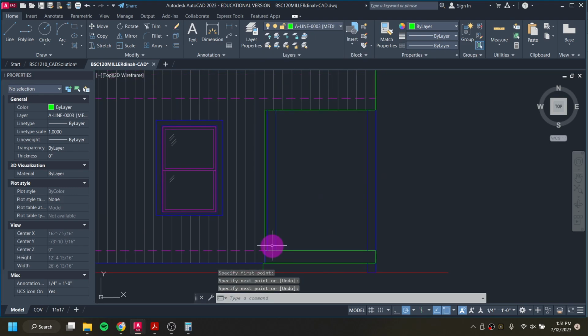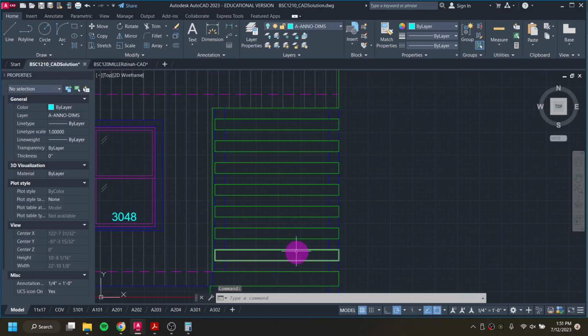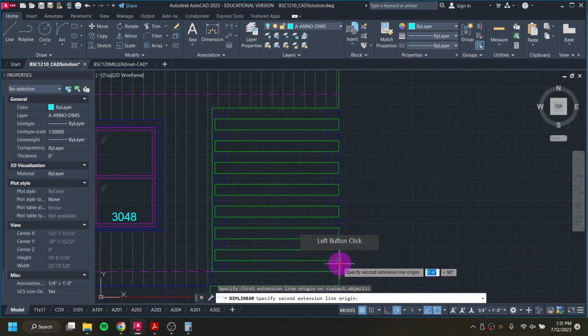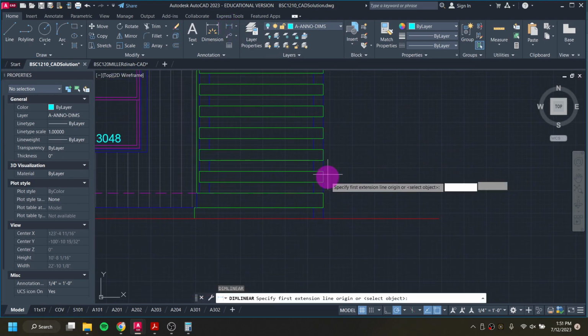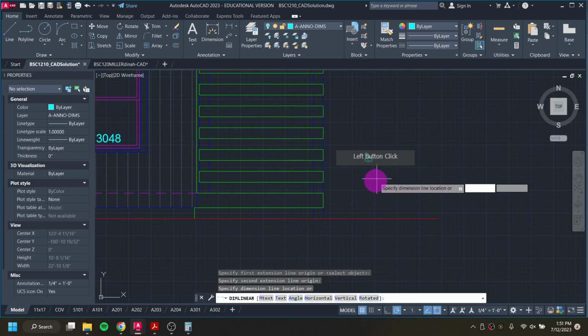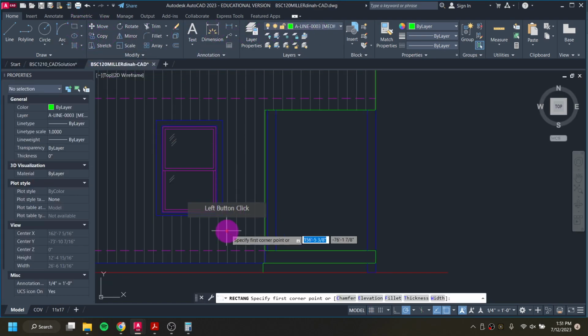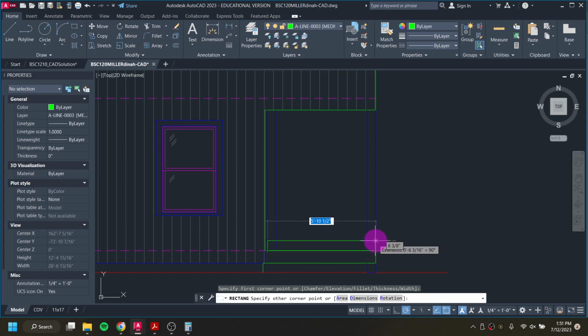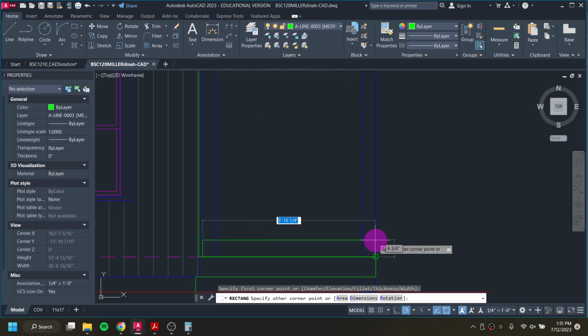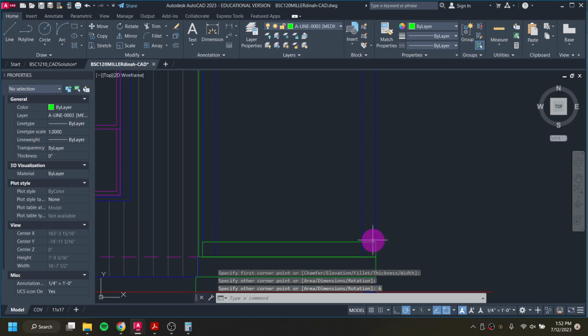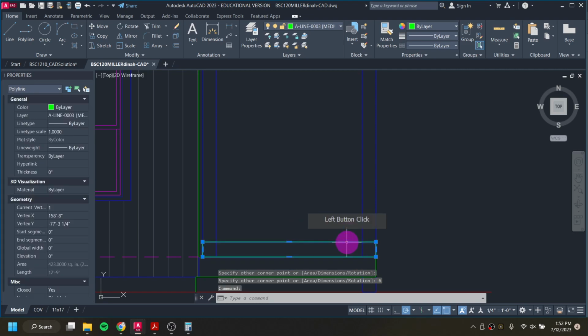And then when it comes to those boards that are sitting across it, there's a 6-inch space and there's 6-inch boards. So if I come here to this, we have a 6-inch space and a 6-inch board. What I would do is draw a rectangle that is 5'10.5", because if I started in this corner and I go across to that, I see that it's 5'10.5". And then tab 6, enter, and I would copy this.